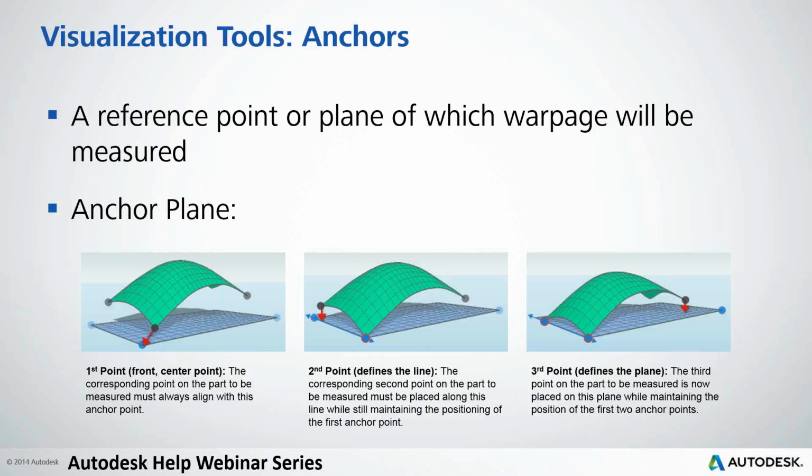And again, Synergy applies an automatic anchor plane to this, and it kind of plays along with that best fit option. So you most likely need to set a custom plane for your particular part or study, and adding several anchor planes allows for you to switch between the different measurements, so you can maybe add different planes to each of the different critical dimensions on your part and easily filter through those.